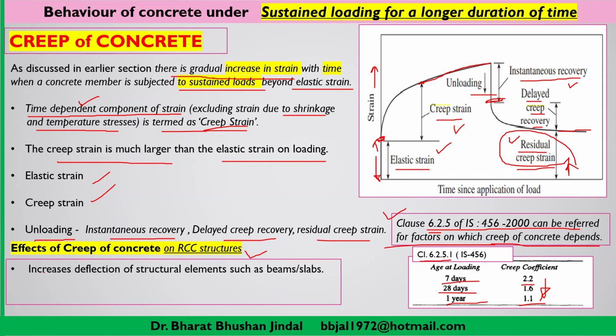The very important point is, when you are going to design any RCC structure, you will first be interested in how much deflection will occur in the member due to the loading. So another effect of creep on concrete is that it will increase the deflection of structural elements such as beams and slabs.